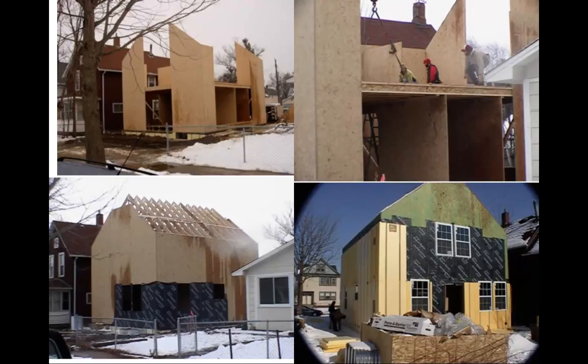So in building this, you actually use your second floor or the I-beam to support the second floor as a bracing system. So this I-beam, as I'm showing with the pointer, actually extends over, attaches to this wall, and keeps that wall from buckling out or buckling in.